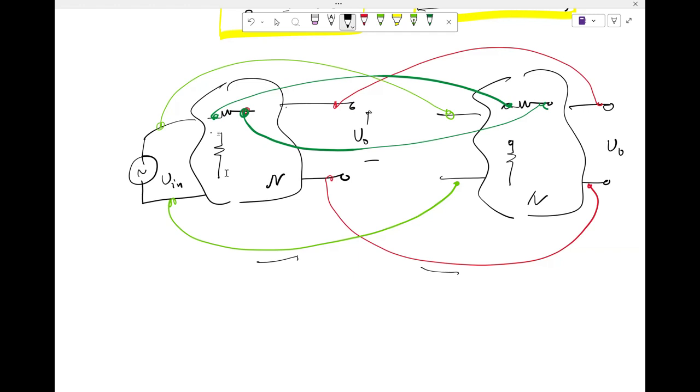All we have to establish is what happens to the noise, because each of these two circuits has noisy resistors inside. I established the signal transfer function does not change. If I can establish how the noise changes, then I can argue what we should do in order to change SNR. Can you also comment on the power?